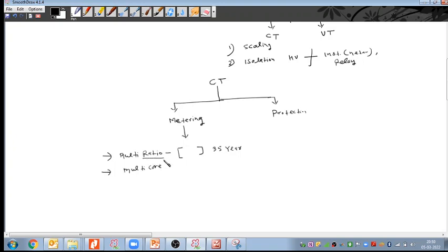And when the plant or the transformer is running at full capacity, we can go to the higher CT ratio. So to get accuracy in the metering and the protections when there are light load conditions in the initial years of the substations, this multi-ratio is useful.